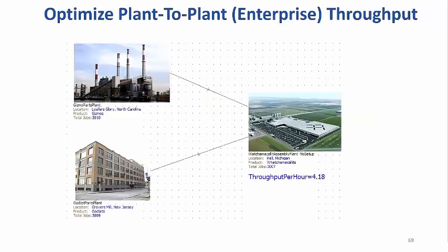At first, you're puzzled. Your whatchamacallit assembly plant model has the latest input data, and the model runs at a bit more than 5 jobs per hour. Then you realize that the model assumes gizmo and gadget parts are always available from the sources in the model. So you use PlantSim's hierarchical modeling capabilities to quickly create an integrated enterprise model that includes all the latest data from all 3 plants. The top level view looks like this, but inside each plant icon are full simulation models lower down the hierarchy. Sure enough, using the 2 plant models to feed the assembly model results in only 4.18